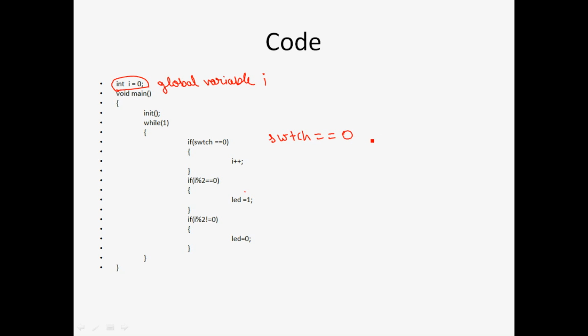So physically, when a switch is not pressed, as we discussed, the pin of the 8051 microcontroller is equal to 1 as per our scheme. When we press this switch, we get the signal equal to 0. So in coding, we can check our pressed or unpressed status with the help of this 0-1 logic. If our switch is equal to 0, that means this switch is pressed.